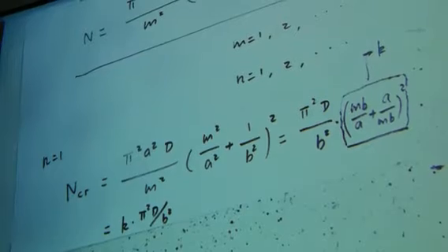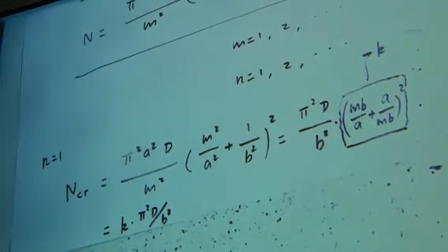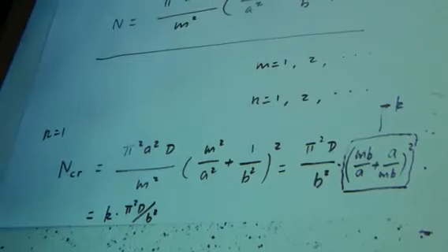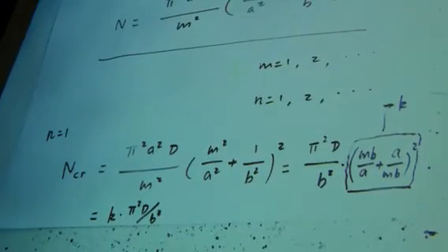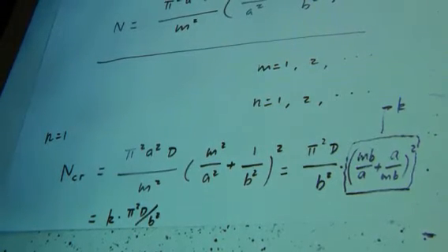So in homework, I'm asking you to model the plate with different ratios between the width and height of that plate. 3 different cases in homework. We are going to do this in Abaqus. You will see the shape will be different because the buckling coefficients will be different. Buckling coefficient is different because the ratio between the width and height is different. So you can check this after you finish your Abaqus modeling.